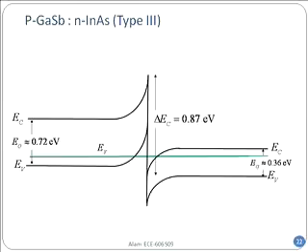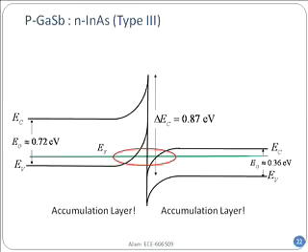And you can correspondingly see that in this region, very strange things are happening. There's no depletion region per se. On both sides, carriers have accumulated. On the left side of the junction, what has accumulated? A huge amount of holes have accumulated. On the right hand side, what has accumulated? Electrons, because look at the Fermi level, the green Fermi level has gotten inside the band.